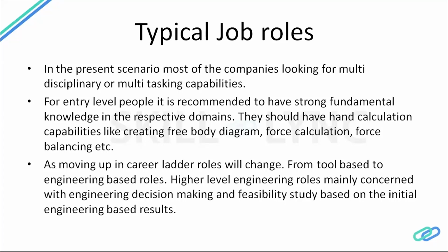many times. As I said, your calculation part has to be done correctly, the mesh part has to be done correctly, the loading part has to be done correctly, force balancing you need to check, and you need to have convergence, stress convergence, or whatever convergence you can do. After that, you need to come into some stages.